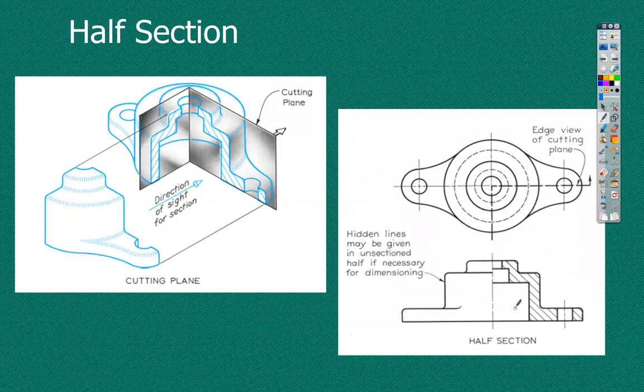Even though the sectioning tool inside of Inventor is in the 3D workspace, where we'd call this a quarter section view, a quarter view, on a drawing it's a half section. This view is a half section. Don't get confused between what they call it in the 3D workspace and what they call it on a drawing. So those are the two main ones.